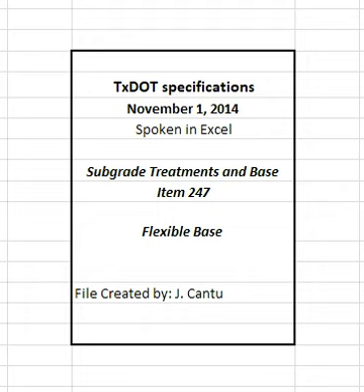5.5 Ton. By the ton of dry weight in vehicles as delivered. The dry weight is determined by deducting the weight of the moisture in the material at the time of weighing from the gross weight of the material. The engineer will determine the moisture content in the material in accordance with TEX 103E from samples taken at the time of weighing. When material is measured in trucks, the weight of the material will be determined on certified scales, or the contractor must provide a set of standard platform truck scales at a location approved by the engineer. Scales must conform to the requirements of Item 520, Weighing and Measuring Equipment.